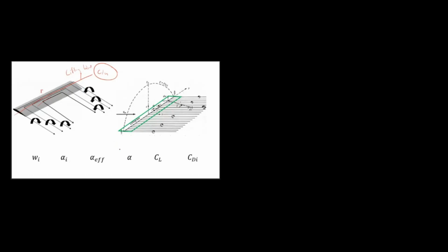This theorem is called Prandtl lifting line theory. To derive the expression, he made some simplification. Instead of spreading the vortex filaments, he superimposed all the vortex filaments in a single line. The line is called the lifting line, so this theorem is called Prandtl lifting line theory. So finally, we will get the profile like this, even the same line.